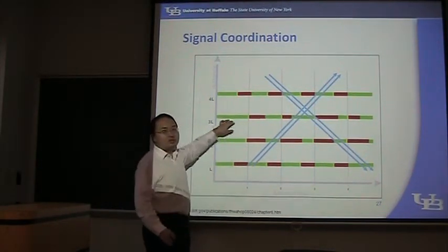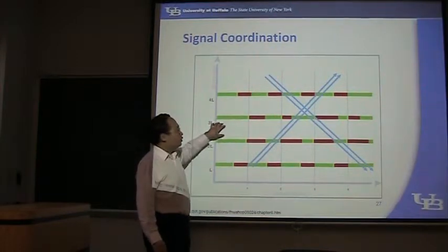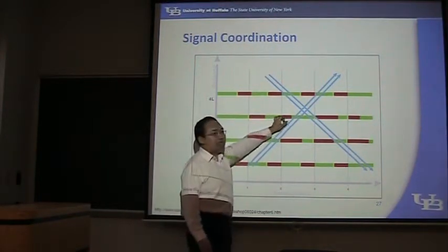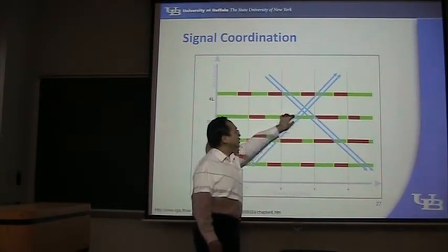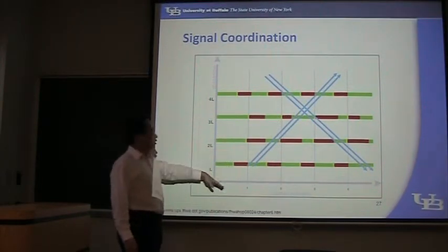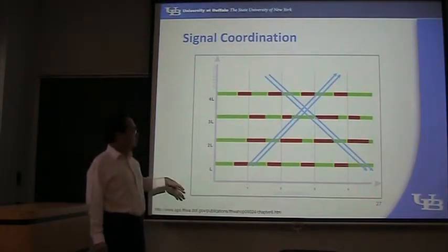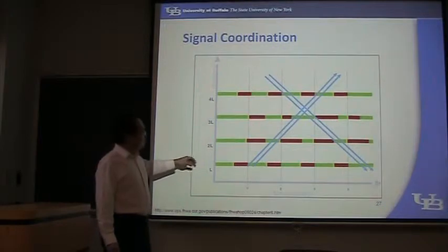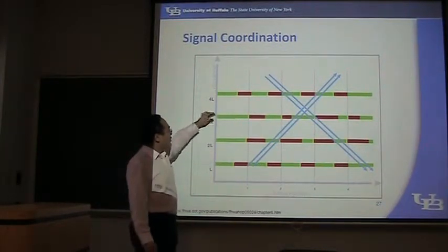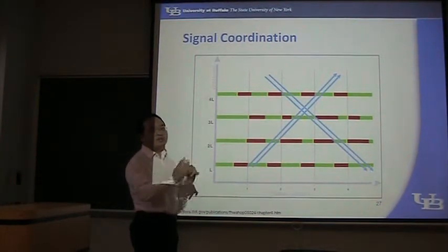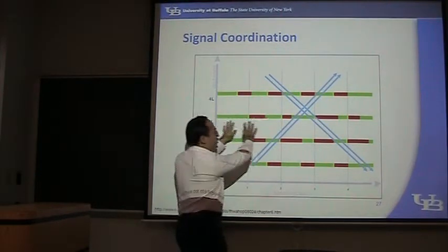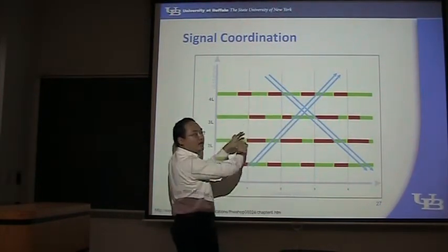By offsetting these traffic signal phases, we will be able to change the width of the bandwidth of these 4 intersections. Do you understand this? So let's say for example, this intersection, the phasing plan is fixed, but we can move it left or right.